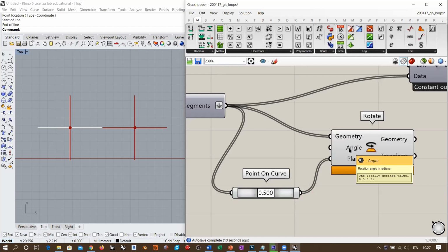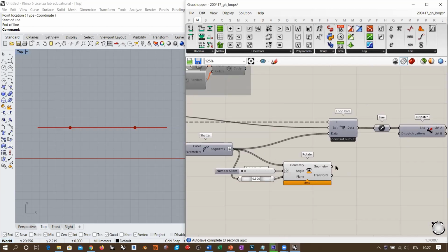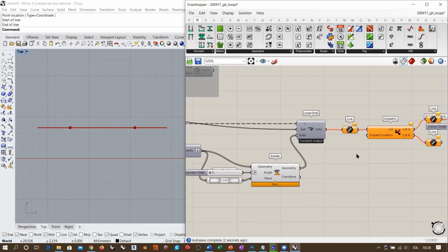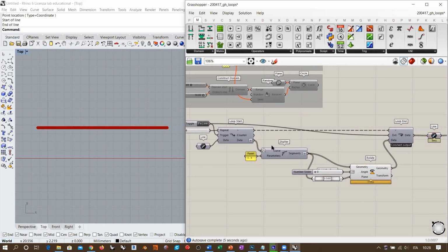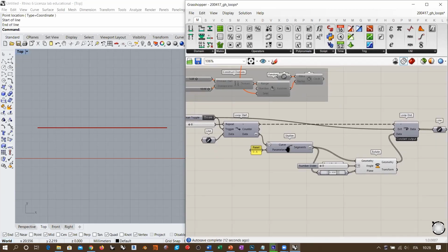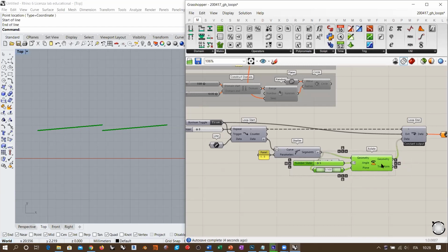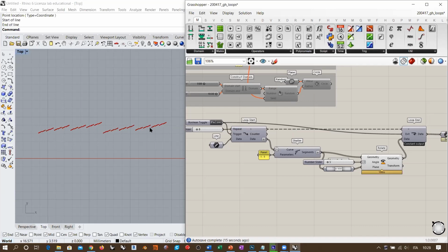because the angle is set to 0.5 multiplied by pi. But I want this angle to be variable, so I'm going to switch to degrees, and I'm going to use, for example, a slider between, I don't know, 0 degrees up to 90 degrees in order to have an extreme rotation, okay? Of course, if I have 0 degrees and I plug this here, there is basically no change in the loop, because when I fire the loop, I still have the same result, because there is no rotation. But if I increase, for example, let me stop the loop, and let me set this angle to a small value, like this. Each time that I run this loop, each iteration, the new segments will be rotated a little. So if I do this, you see that segments are being shattered, and they are also being rotated